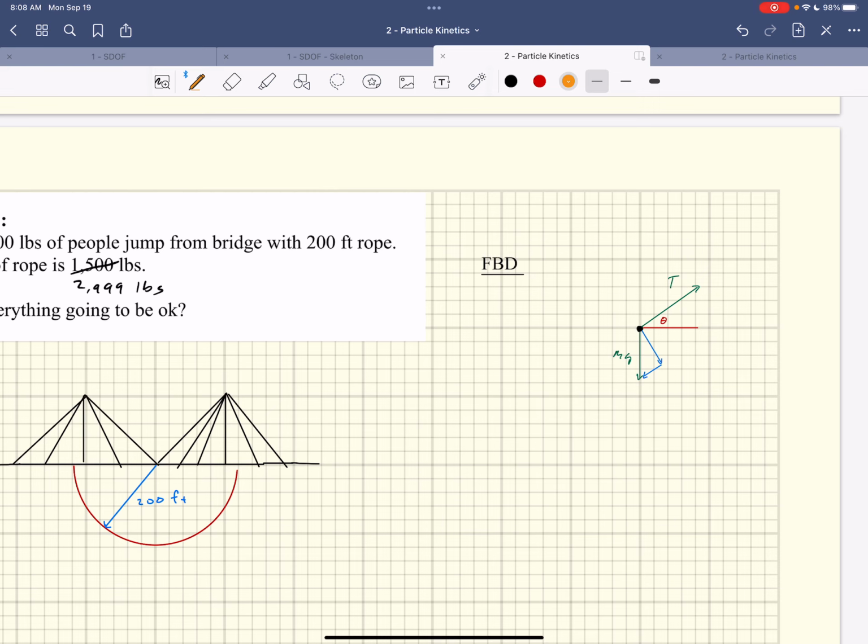So our coordinate system is going to go like this. We're going to have something right here, a tangent there, and then normal pointed back to the middle. This is e_t, and this is e_n hat. And so over here on our free body diagram, this is going to be e_t, and this will be e_n. Everybody see that? One's tangent to the path, and one's normal to the path. So it's like that. e_t is going down, e_n to the.